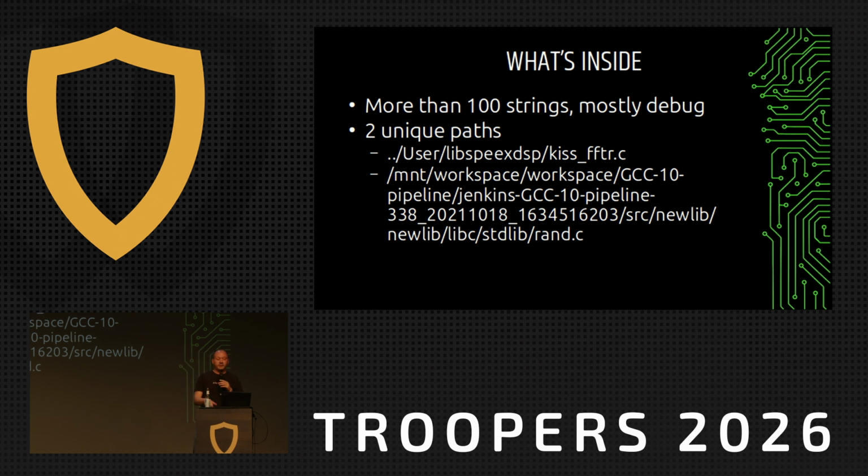By the way, randomization is used in protocols like that for two things. Well, if it were used for cryptography, that would suck, because this is not a cryptographically secure randomization. The other thing that it can be used for is anti-collision. Basically, it's a bus system. There are many devices. If all of them were going to communicate after a preset amount of time, we would have collisions all the time, which means that they tend to randomize the delay before they send some data on the wire. That's where the randomization function is usually used.